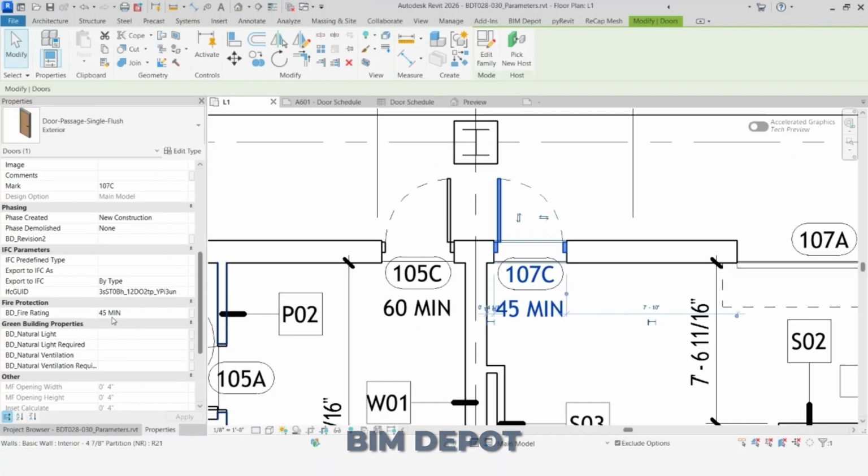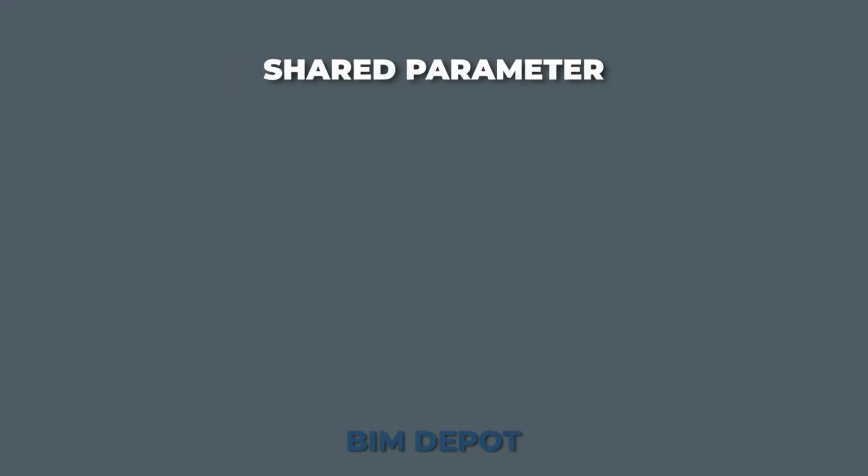Let's discuss some of the pros and cons of using shared parameters. The pros, so this is something that's standardized across projects, teams, and families. This is really something that you're setting up early on, adding to as needed, and then that gets reflected kind of across the projects. They're not linked to specific projects, so if you do have to make an alteration, it's not like you're making alterations to a series of different families or a series of different projects firm-wide. It's just something that is controlled when you're setting up the beginning of your Revit.